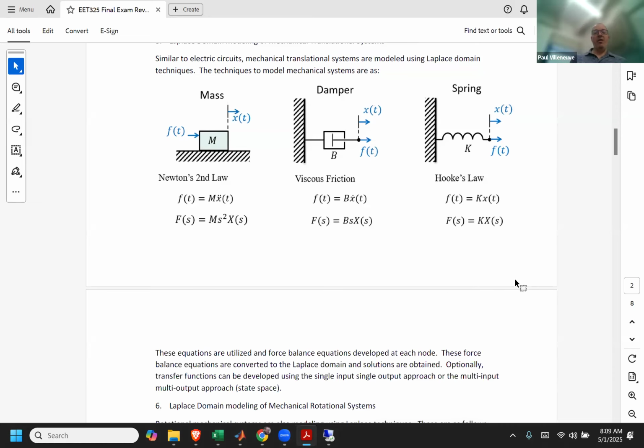But yeah, and so to do all these problems, you just do force balance. Force balance about an operating point. So pick a point, figure out the directions of the forces, sum them, right, including directions, because now we have to be mindful that things may not be going all in one direction. They can go in different directions. And then you should be able to do transfer functions for whatever.